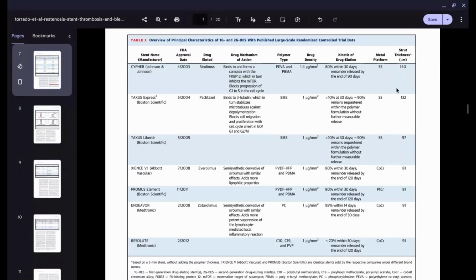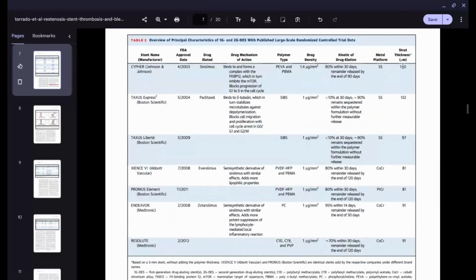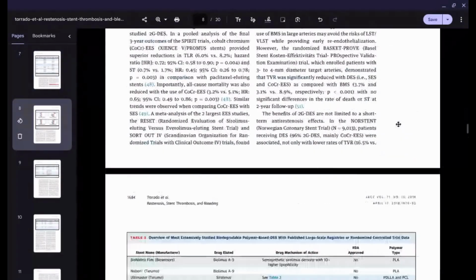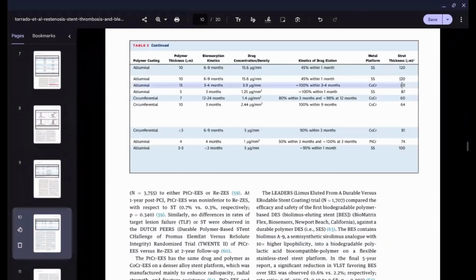It's also the same. In fact, one of the conclusions is that if you make biopolymer stents with thickness similar to that of metals, they are going to fail easily. They are degradable to start with. Fatigue and all that is really out of the question. So at least you need to make the thickness greater.